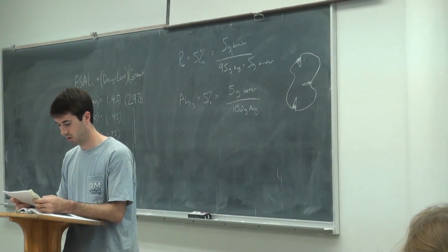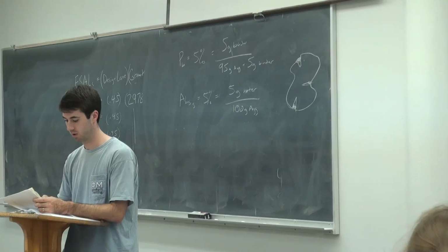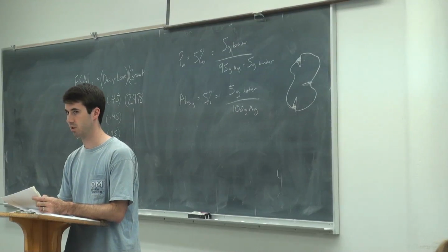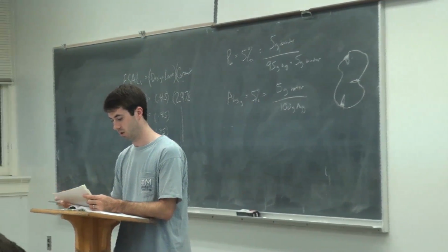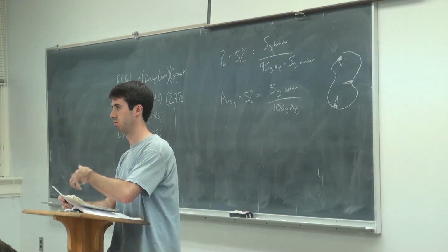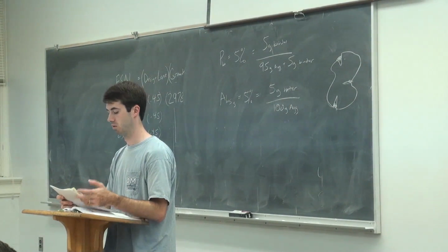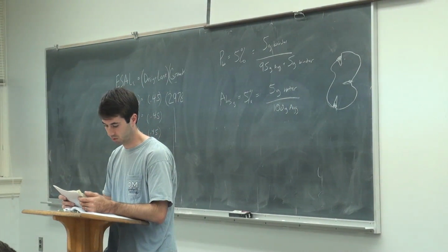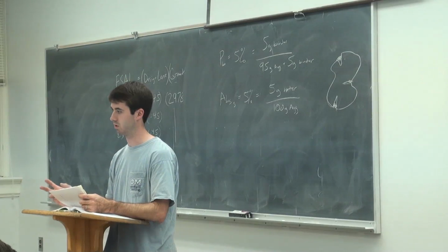And it gives you this value, G star over sine delta. G star is the modulus, the delta is the phase angle, which like for steel would be 0, for water would be 90 degrees. So it's just a way to kind of characterize the whole viscoelastic thing in binders.